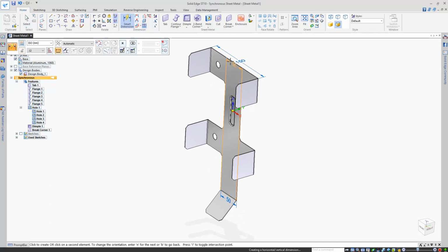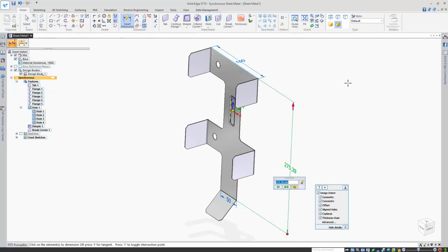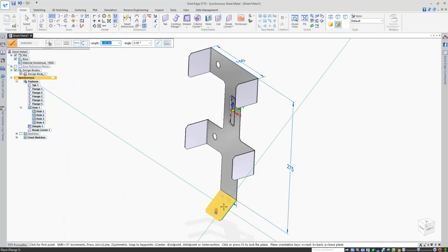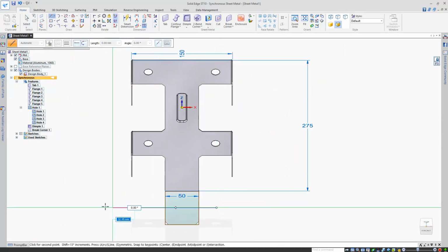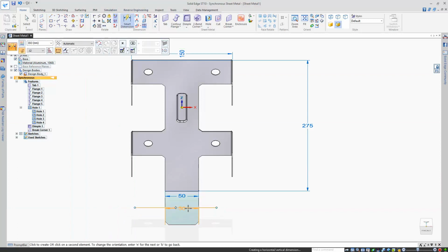The bottom flange now needs a jog in it, but this also needs a sketch. But to create a jog, all I'll need is 1 line. In this case, a straight line 25mm from the bottom edge of the flange will work. Once again, I don't care about sketching neatly, as the sketch is just going to be hidden after it's used to create the feature.